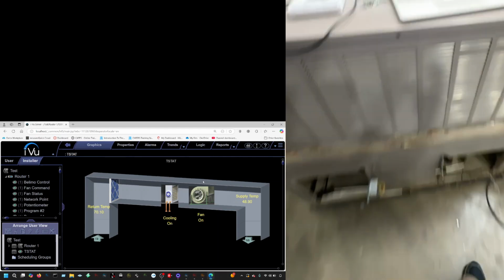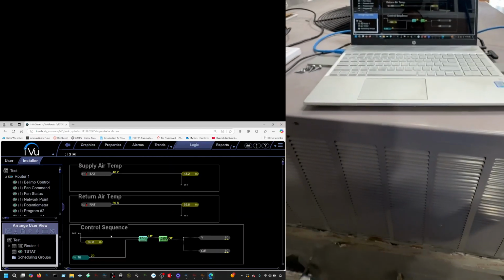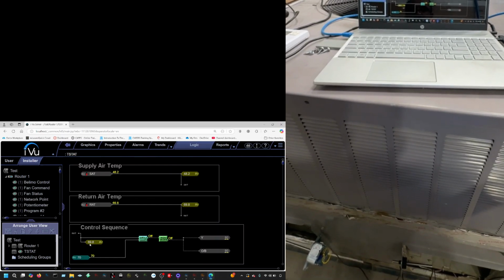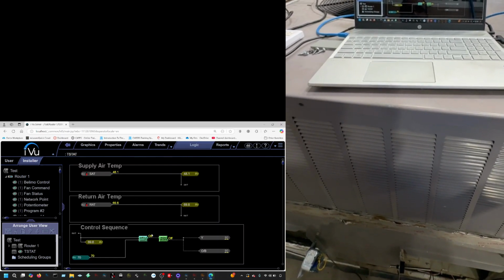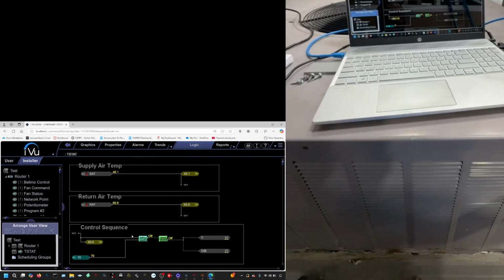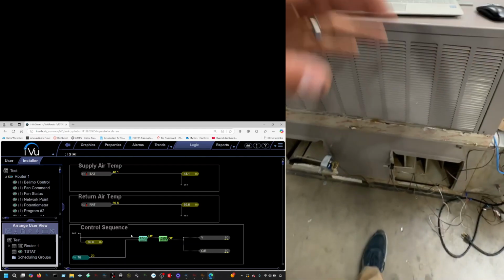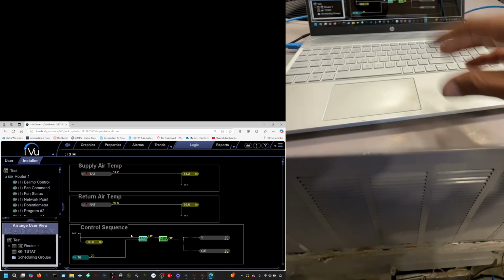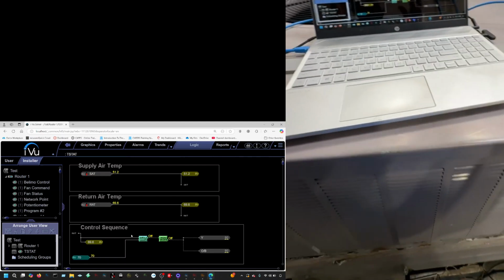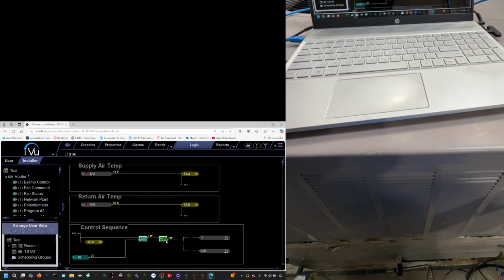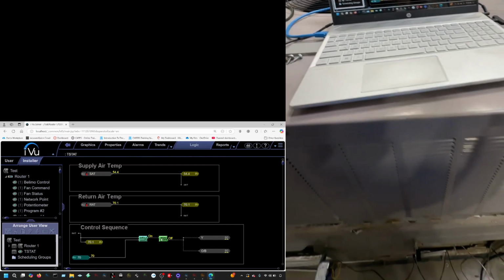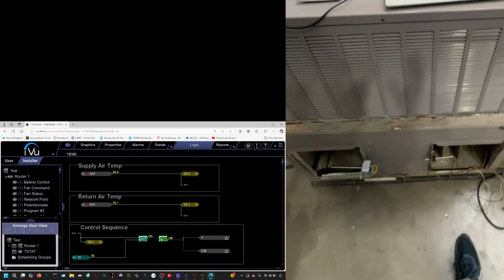You see, and just like that, it turned off because we're below, right? 69.8 is not greater than 70. So then I am not going to have an on signal. So it's going to be doing that on and off, on and off. Of course, this is just a basic program. There's other parameters, other things you do, so you don't have this issue. I kind of messed up, maybe on the minimum on and off block, so I gotta fix that. But you guys get the point.